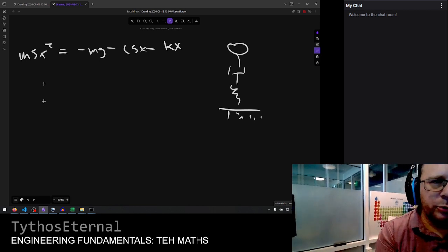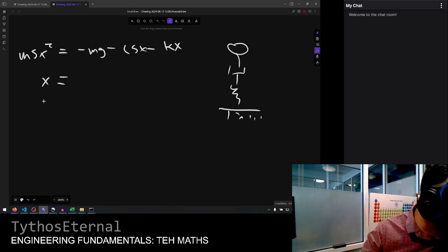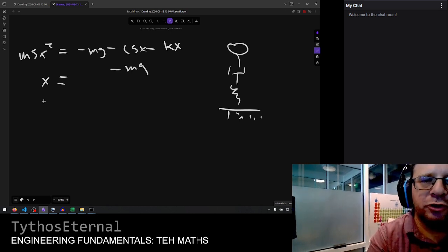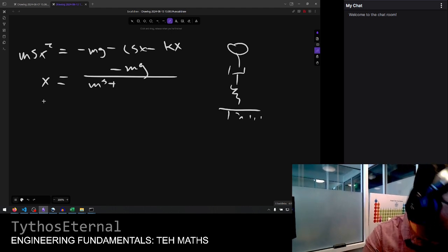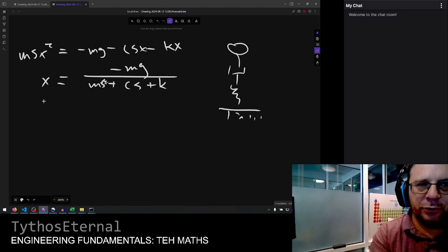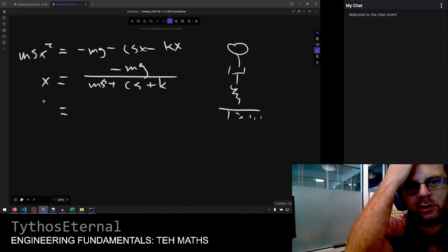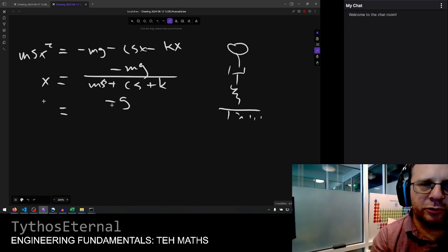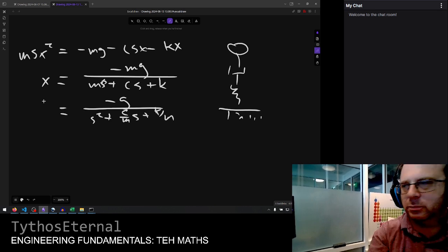Okay, so rearrange, this ends up being g over s squared plus cs plus k. We typically want the first term to be just s squared, so we would pull m out of the top and the bottom. Fortunately, that ends up simplifying things quite a bit. c over m. A lot of these values that you'll see end up being ratios between different properties of the system.